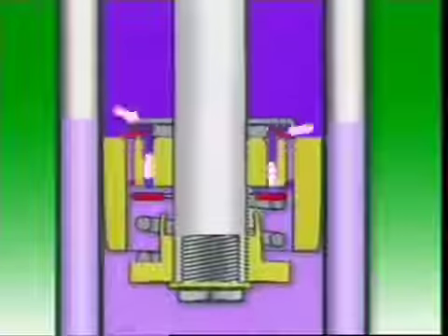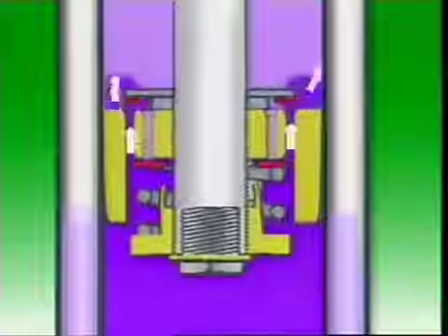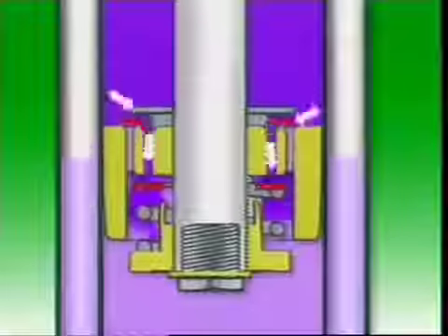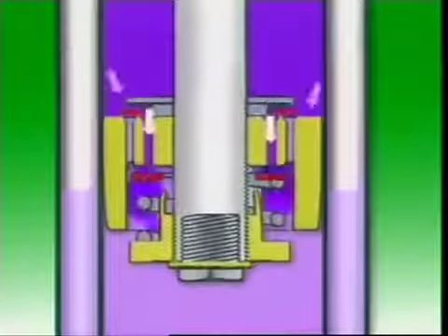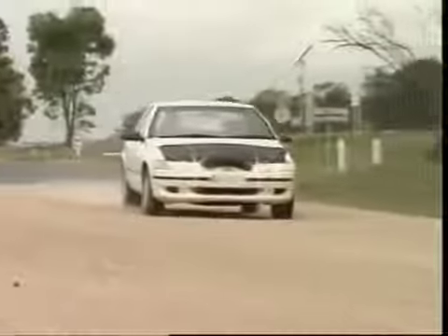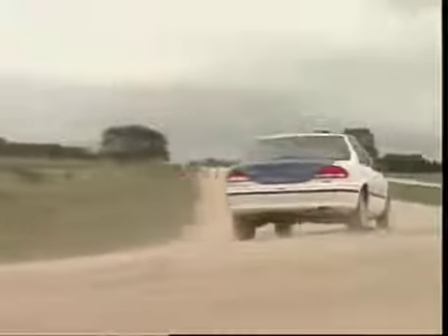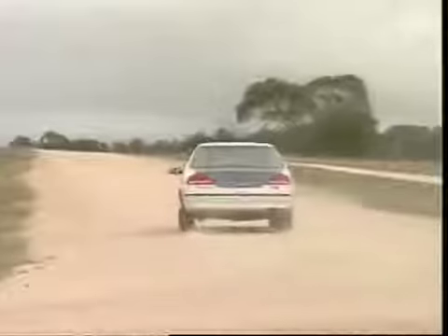However, the hotter the oil becomes, the greater its tendency to aerate. Aeration occurs because of the high velocity of the oil as it passes through the small passages in the valves. If the velocity is high enough, air dissolved in the oil comes out of solution as small bubbles and forms a foam. Aerated oil has a certain amount of compressibility, so it is unable to provide the dampening force previously achieved in the non-aerated condition. The performance of the shock absorber is thus considerably reduced. This effect is called shock absorber fade.